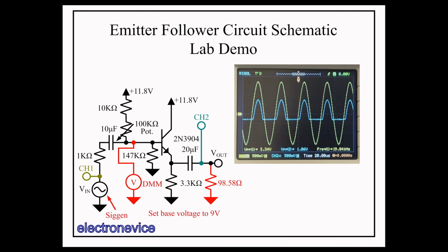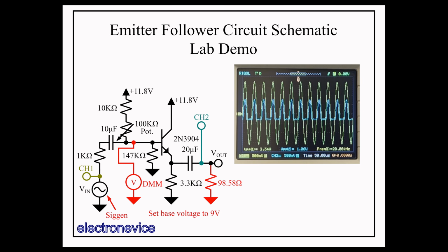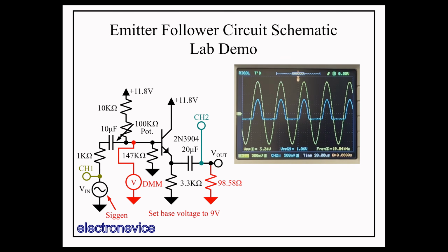At 20 kHz, the output looks exactly the same, so it's not a frequency effect. Ideally, you would use more advanced methods of determining output impedance, like a sinusoidal current source where you measure the output voltage and current simultaneously using something more precise than this scope. But this test gives you a general idea of the properties of this circuit.